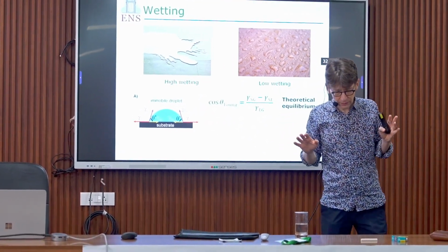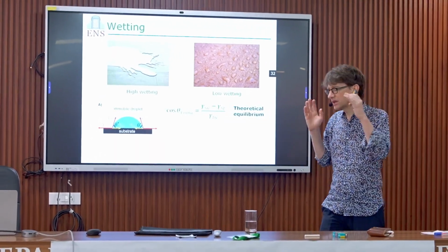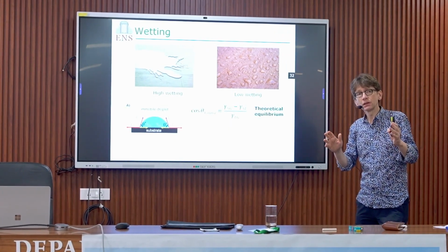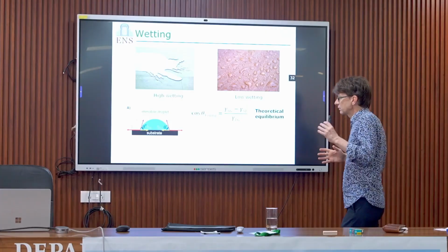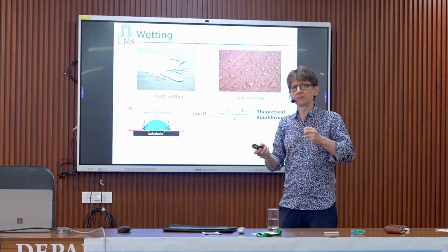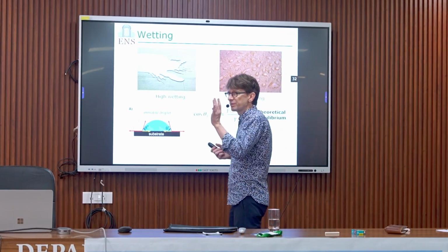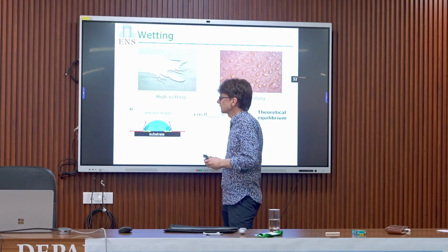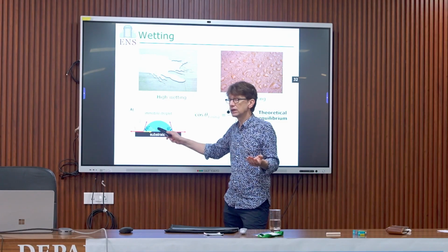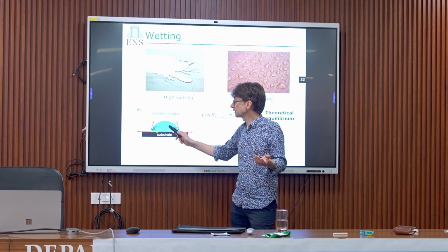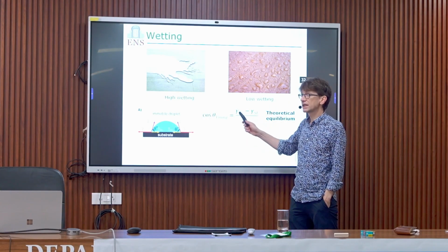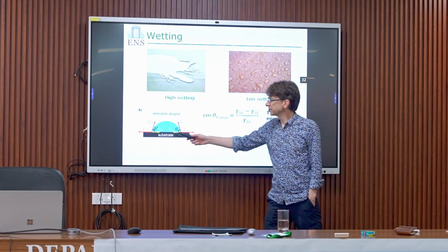So this is very simple. It's quite interesting, and keep in mind that in the contact angle, you have three interfaces. Always. This is something we tend to forget. We speak many times about, oh, I have a hydrophobic material. No, please speak about contact angle. Because if you speak about a hydrophobic material, you consider only this interface, solid-liquid. But for your contact angle, you see that the solid-liquid is here, but the solid-gas is very important. The material is here and is here.